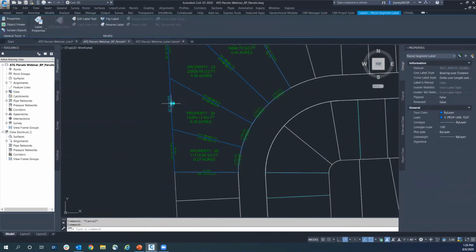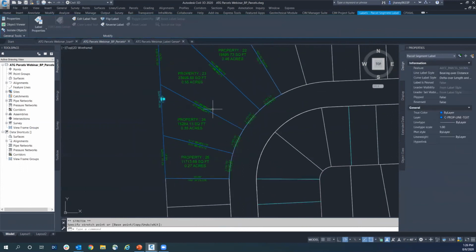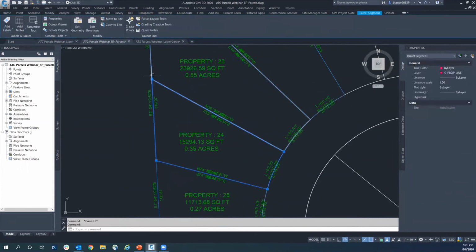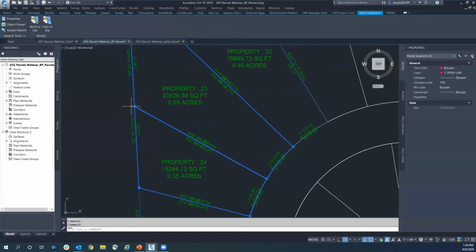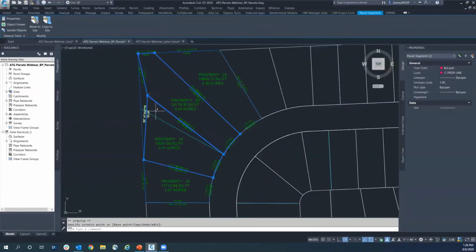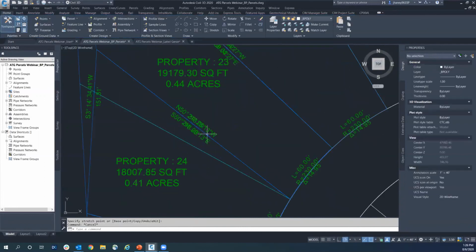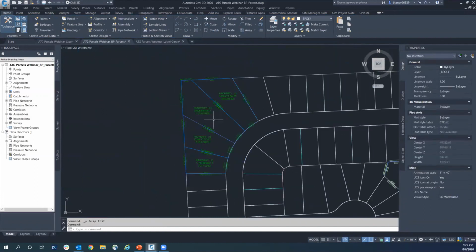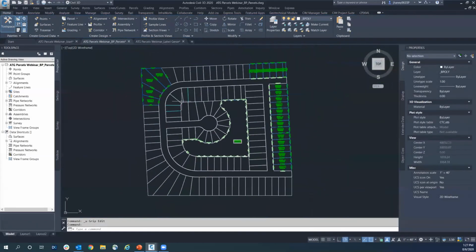So these labels are the exact same as the other one. So if I was to switch this, now you guys know parcels, so if I come in here and do something weird, sometimes it might create another parcel where I don't want it. But see that overlapping labels, it takes care of all that. So that is our Label Genie and creating parcels with a B-poly.